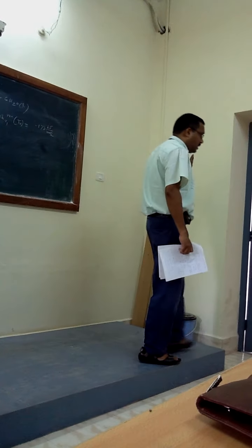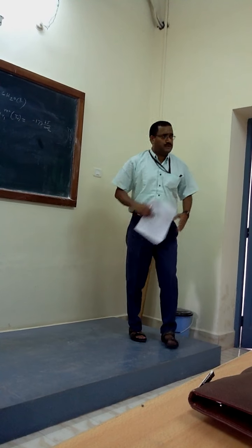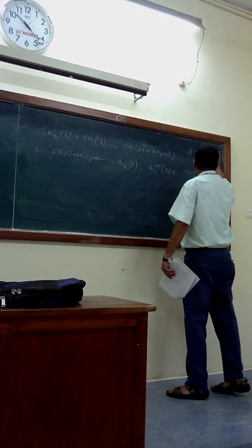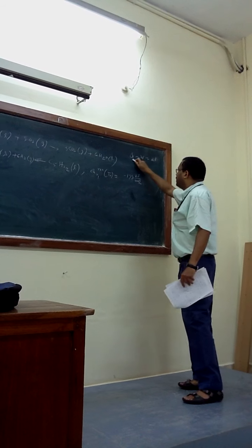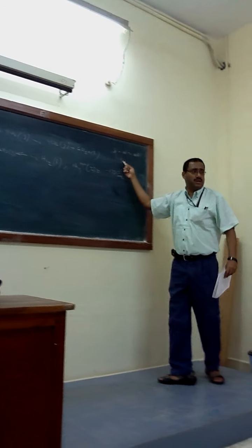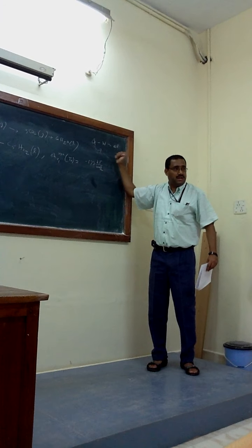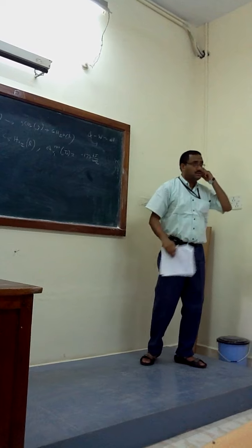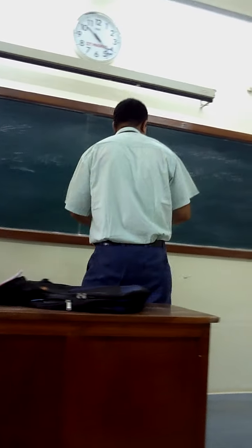For example, what is the first law of thermodynamics? Remember that? Q minus W equals delta E or delta U. And Q sometimes should be indicated in the heat of reaction. So you need to have the net enthalpy change here. You cannot put per mole. Then you have to be very careful, and it is coupled with the first law of thermodynamics. I am not doing it here in the class. So these are the fundamental things you have to know.